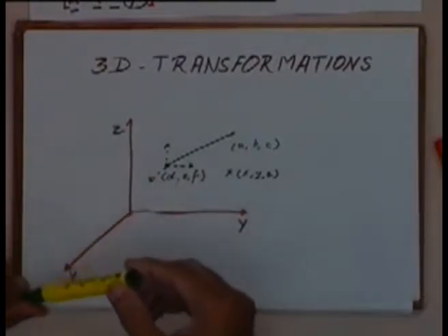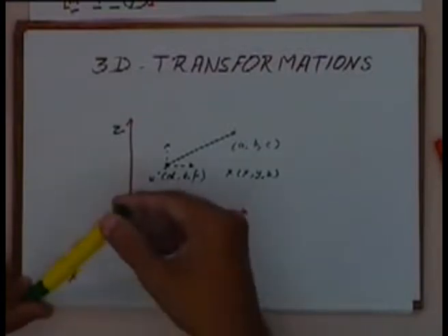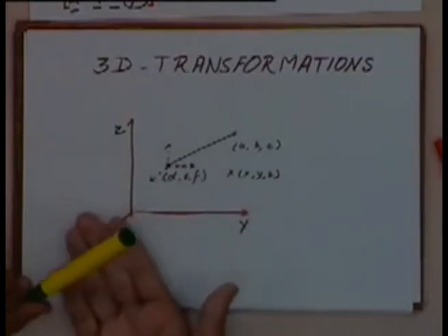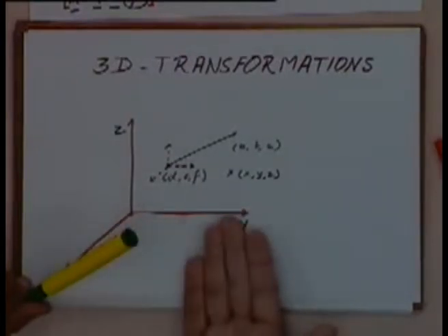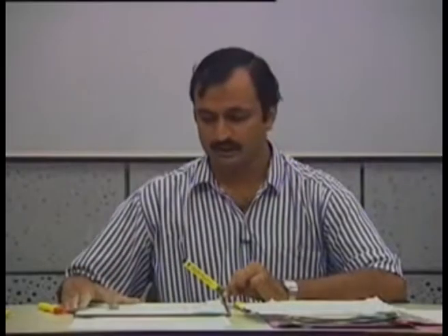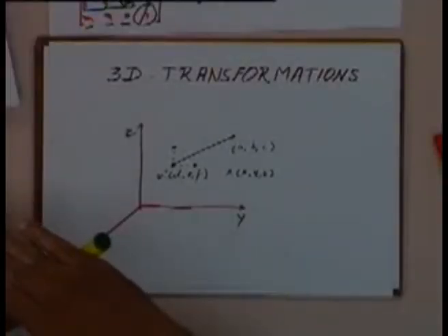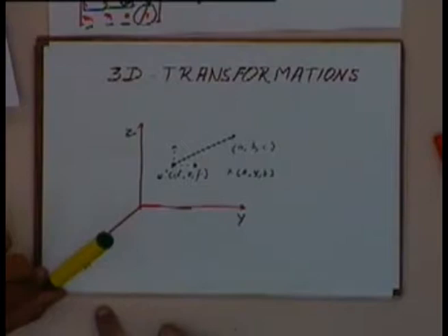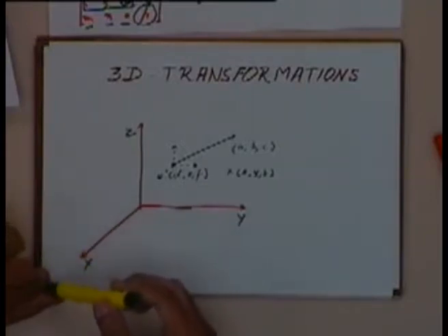From this point, as I will rotate it in this manner, the angle by which it will be rotated will be an angle which I will be seeing as a projection in the bottom plane. Okay, I will again repeat, if I look at the top view of this vector, whatever angle I see in the bottom plane, that will be the angle by which I have to rotate this vector so that it will come into this vertical plane.